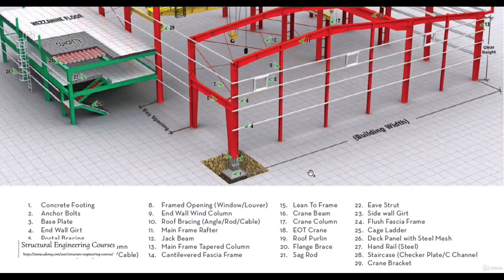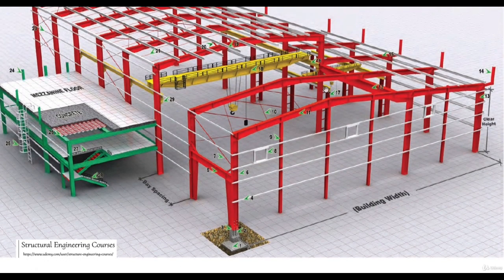And number 17 is the crane column. So this is basically called a crane column. That's this small thing here. There's another EOT crane here from this point to this point. But what they had done is that they had supported this bigger EOT crane on the columns of these portals with the help of the crane beams. But they had made a separate arrangement, that is, the sole purpose of this column is to support this crane beam. So that is why it is called a crane column, and it might be somewhat smaller in size, and the capacity of this crane must be in the range of 2 to 4 metric ton, not more than that.